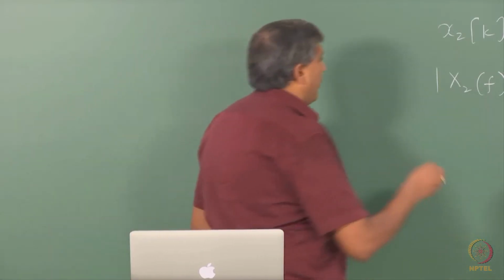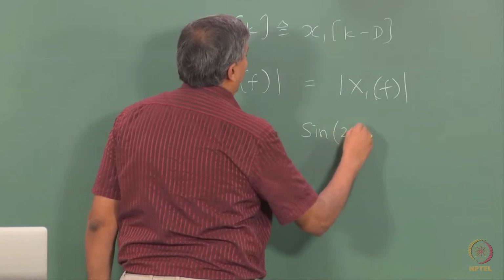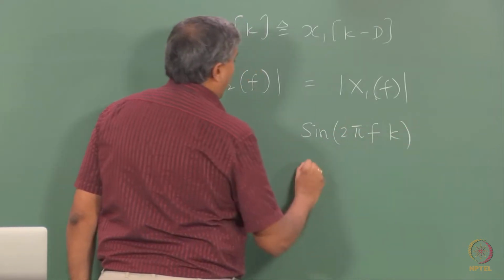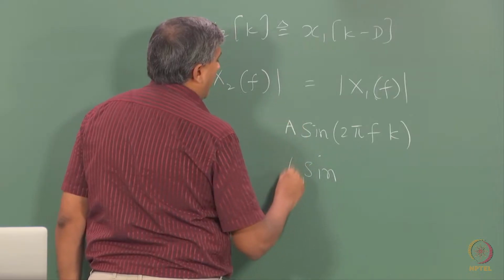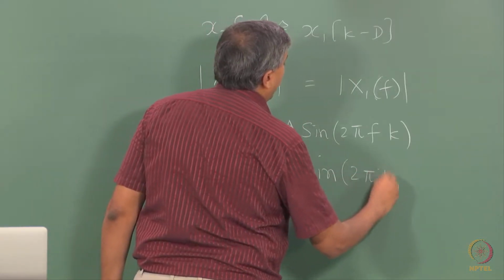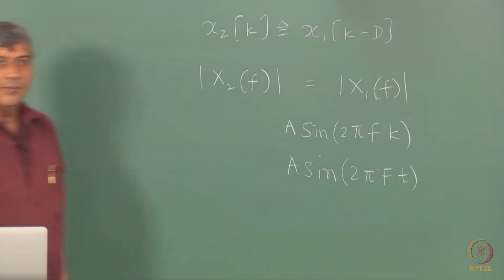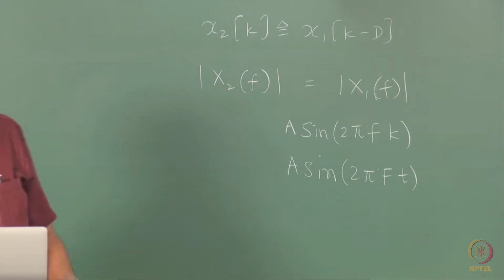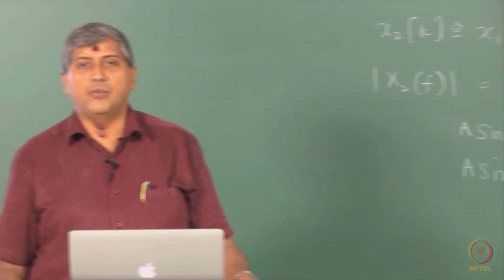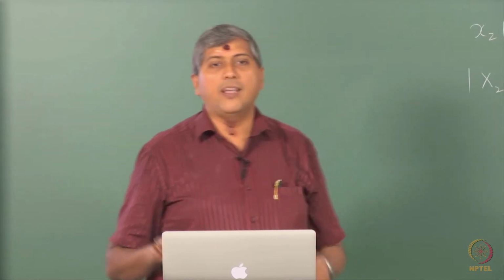Go back, that is why I asked you this question, I am sure many of you are not familiar with it. So, compare these two signals, this is a discrete time sine wave and here is a continuous time sine wave, right. So, now can you be correct in specifying the units of small f? Cycles per sample, very, very important, right. Whereas big F has the units of cycles per unit time, if time is seconds and so on. Both are called hertz, please keep that in mind.